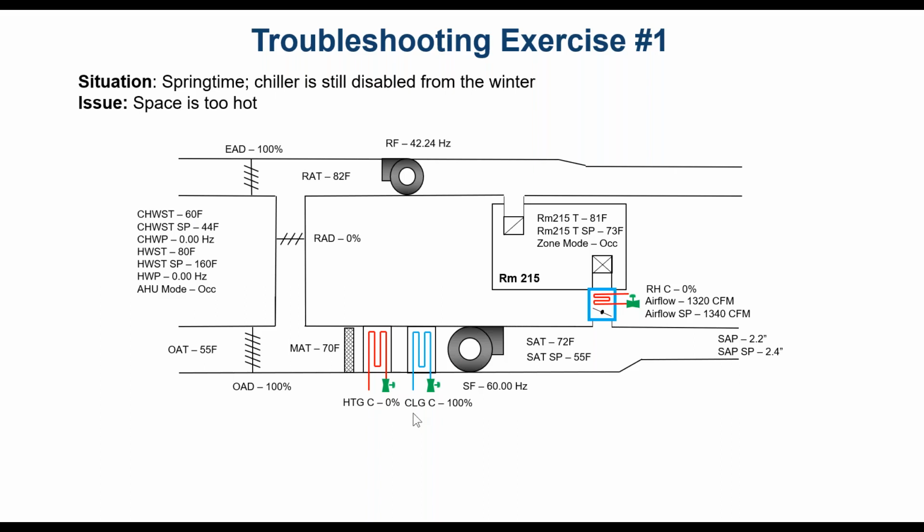Even though the valve's open, the pump is off. We're not actually pushing in chilled water. Well, maybe the heating valve is leaking. Maybe that's the culprit. Well, the heating valve's at 0. Is it leaking? I don't know.